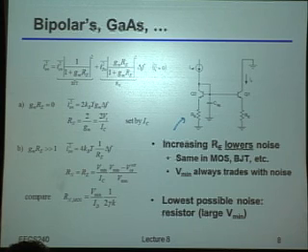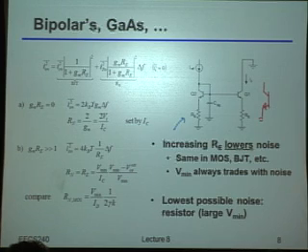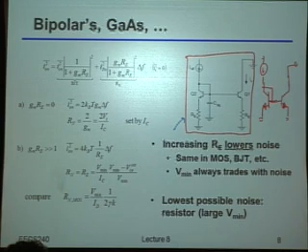Okay, and again, just to be 100% clear, the contrast is the following. I could have done instead something that would have just looked like this. I would have directly grounded the mirror device and also directly grounded the output current source. Right, this would have been the contrast. So, I claim that in bipolars in particular, you really want to use this version of the circuit. In other words, you really want to add that degeneration resistor in. Why is that? Why is it really important to add that degeneration resistor in, particularly in a bipolar current source?